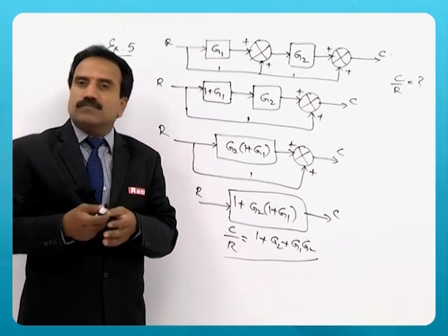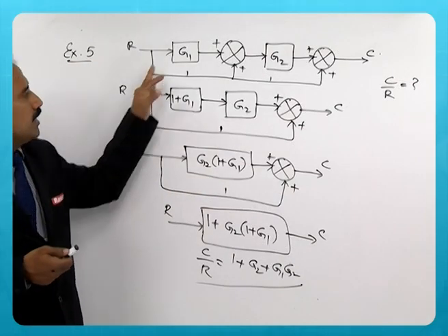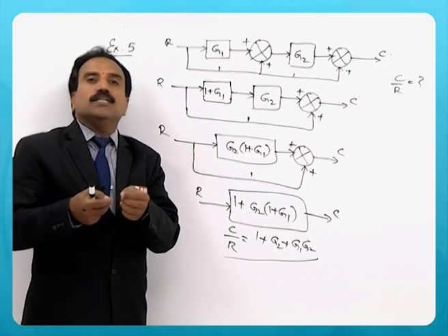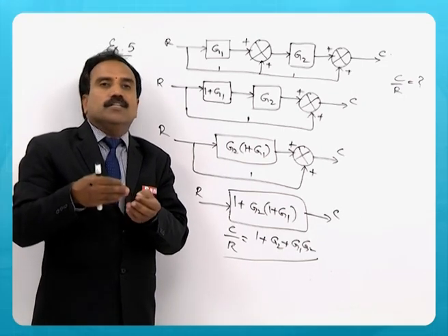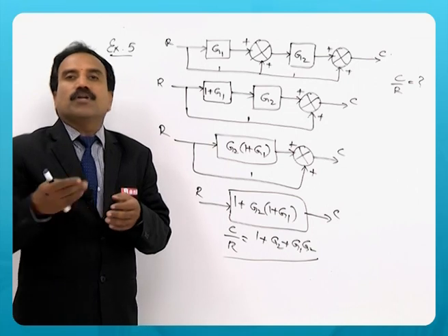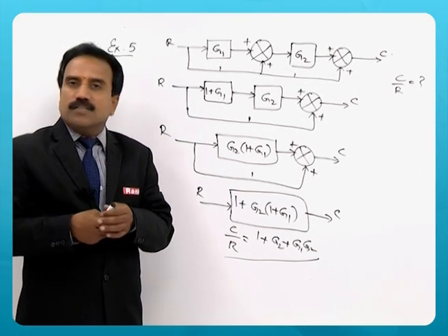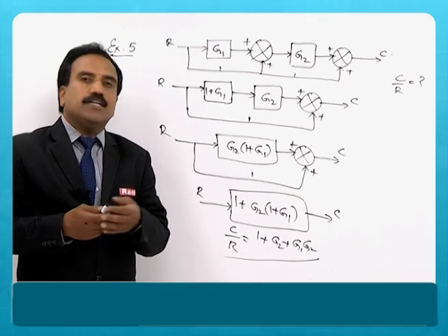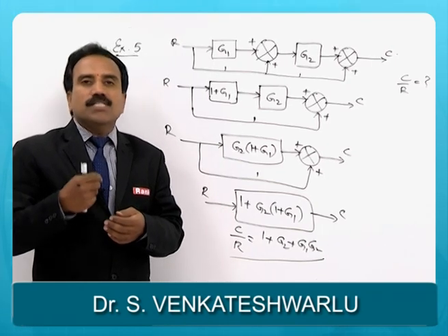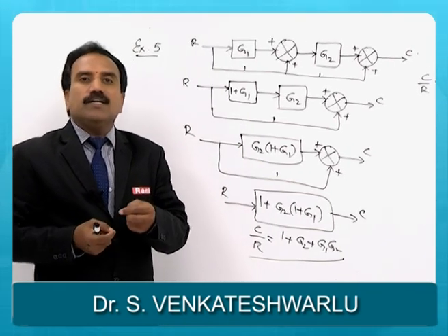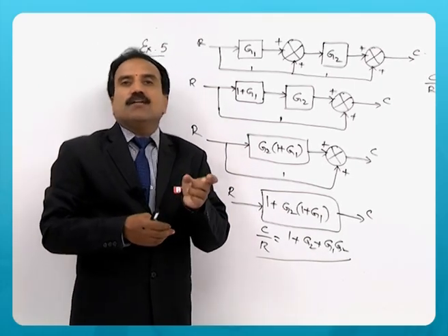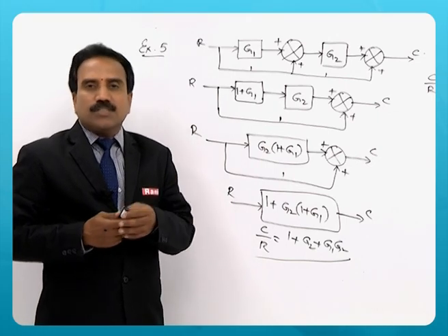It is an alternate version of the block diagram. We have seen the block diagram is very complex. When you are applying one rule, you may have to draw the entire block diagram again, and it is very laborious, time consuming, and not that easy to get the overall transfer function. So we will discuss the signal flow graph approach invented by Mason, a scientist, and he has developed the formula called Mason's gain formula that is applied to find out the overall transfer function of a given system for a signal flow graph. It is a graphical representation of a system.